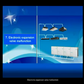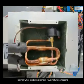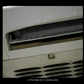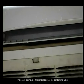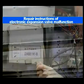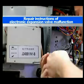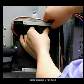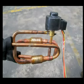Electronic expansion valve malfunction. Normally, when electronic expansion valve malfunction happens, the cooling or heating performance will be bad, or if the indoor unit is in standby mode, the panel, casing, and electronic control box have condensing water. Repair instructions of electronic expansion valve malfunction. First situation: the electronic expansion valve cannot be opened or well closed, and the valve has no sound of action or the sound is smaller.